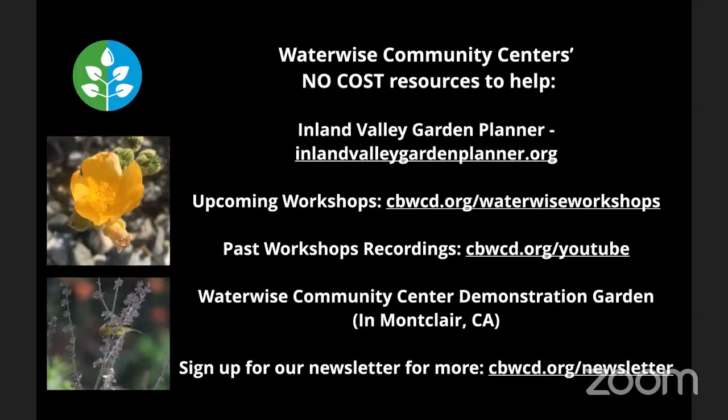In general, with a good irrigation system that is set up to run appropriately and water deeply and occasionally, like our water-wise plants want, we should be able to get the water to penetrate as deep as we need it to without running off. Because if we're going to need so many minutes that it's going to start to run off, we use those multiple start times or cycle and soak that I talked about. I will generally want everything to get a pretty deep soak.